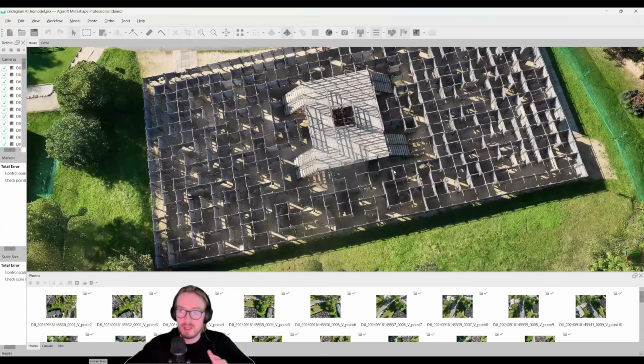Like I mentioned, this whole data set, both Pilot 2 and Circlegrammetry, was flown at about 36 to 38 meters altitude. But what we also wanted to do when we were there was fly at a lower altitude. So we decided to try to capture this whole labyrinth at an altitude of about 20 meters.